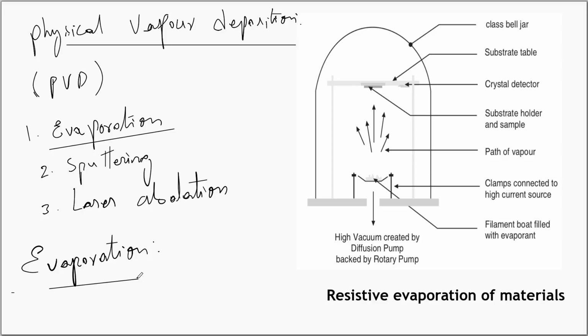In the evaporation method, the substrate is placed inside a vacuum chamber. In the same chamber, we will also have the source of material which needs to be deposited. The source material is then heated to the point where it starts to boil and evaporate. The vacuum chamber is required to allow the molecules to evaporate freely in the chamber. Later on, these vapors condense on all surfaces. This principle is the same for all evaporation technologies. Only the method used to heat the material or to evaporate the material differs.